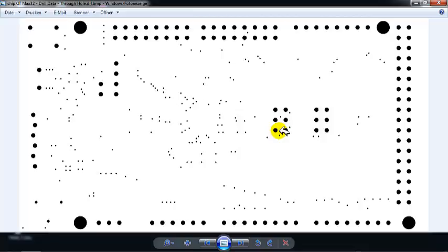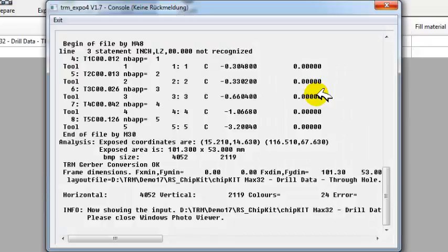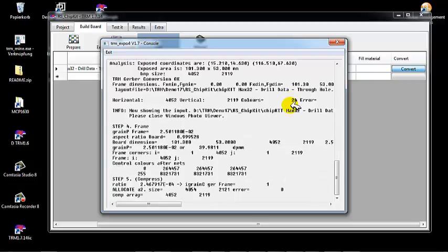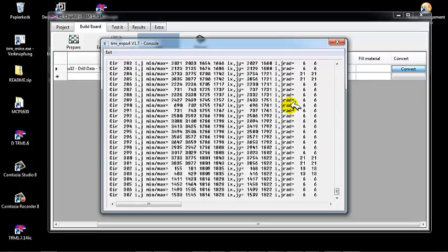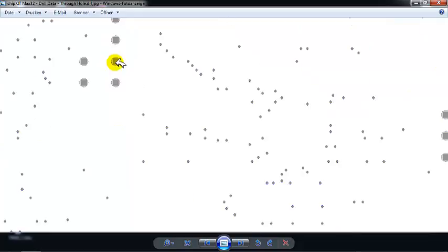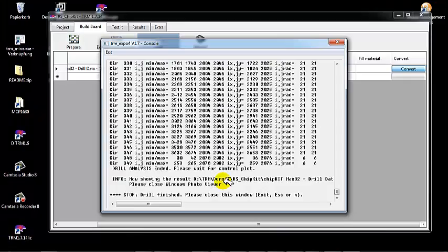A control plot of the Excellon data. Now these circles are converted into effective drills because the 20 micron plating is not resolved geometrically. Instead we build a physical model for each plated drill, and this is represented by the squares embedded in the circles. Now this is done. We have 349 holes.